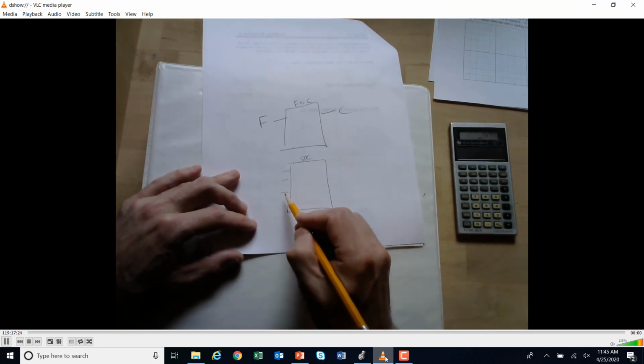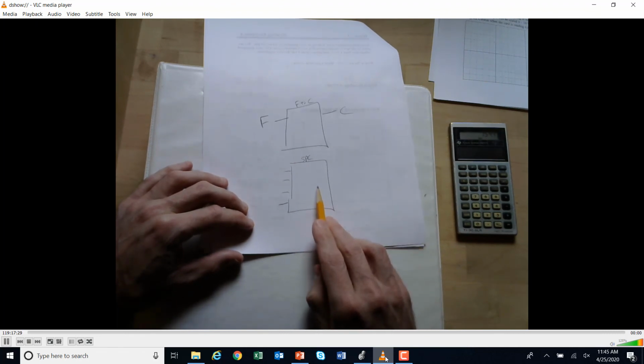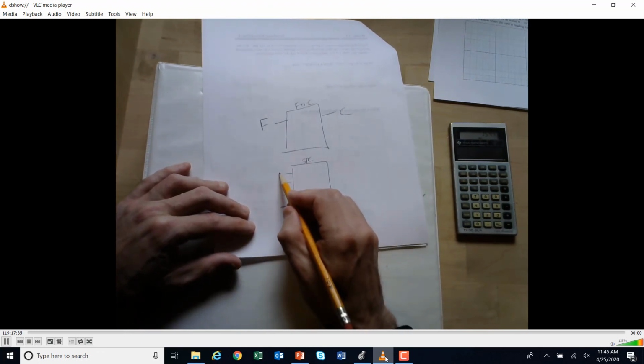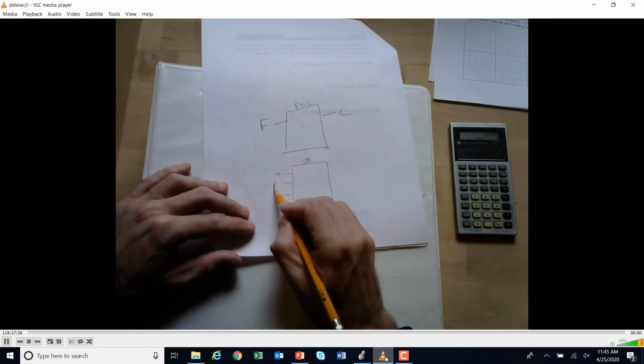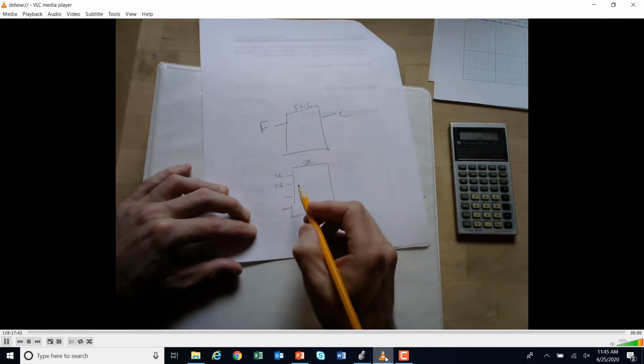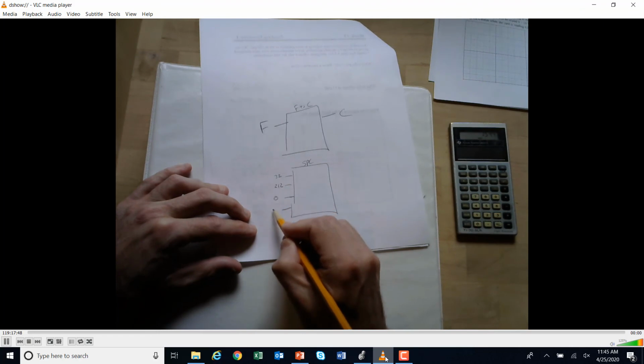And in here, what we're basically going to do is that engineering and that math that we talked about. A minute ago, I showed you an example where we were taking in 32 degrees and 212 degrees, let's say, and then we wanted it to come out as 0 to 10 volts.